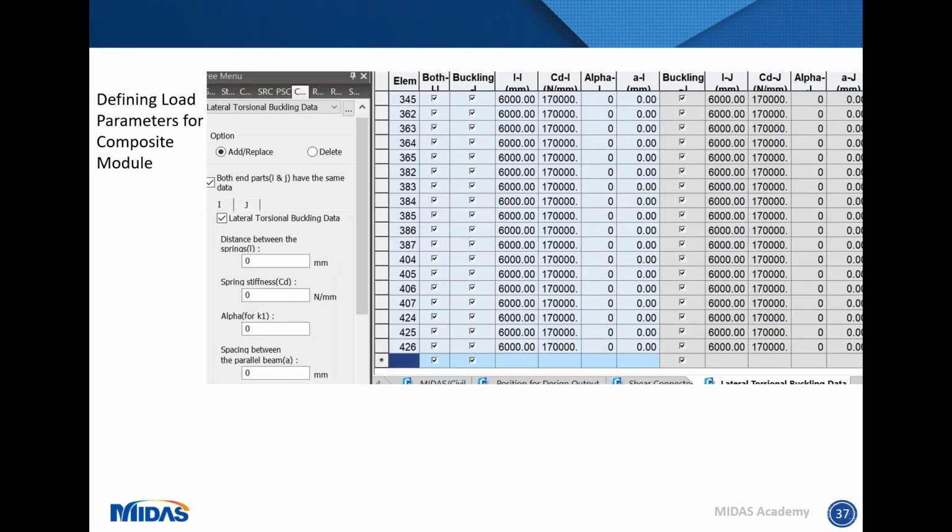And similarly, you can also define elements based on springs within your model. So you do a separate calculation noting the spacing between springs. In this case, for my structure, it was the spacing between the bracings, and in addition to that, adding in the specific spring stiffness for those bracings along with that as well.